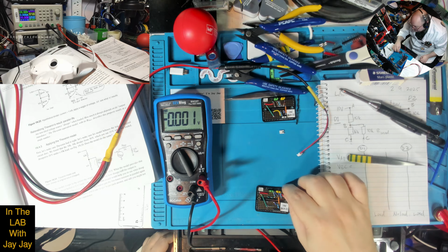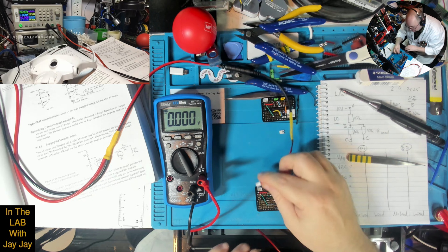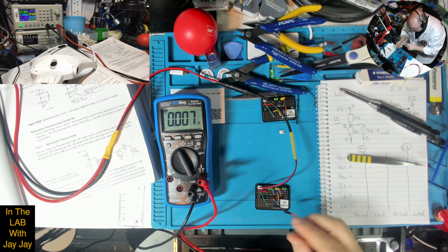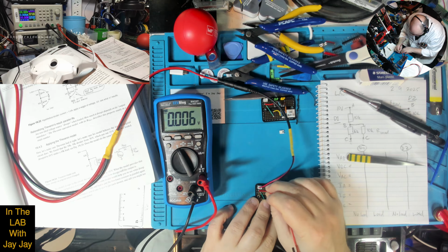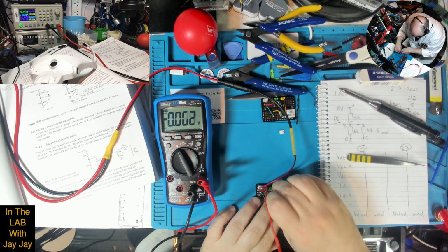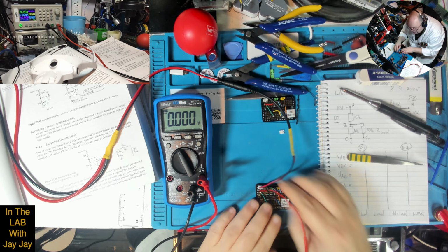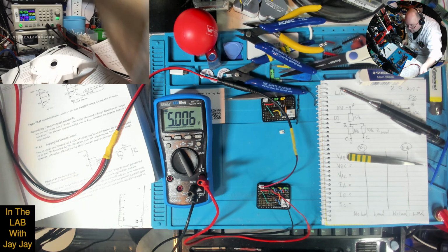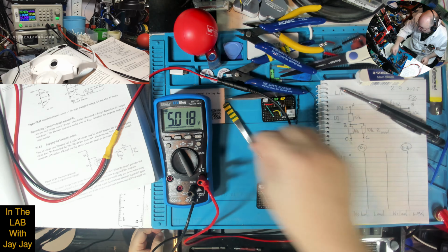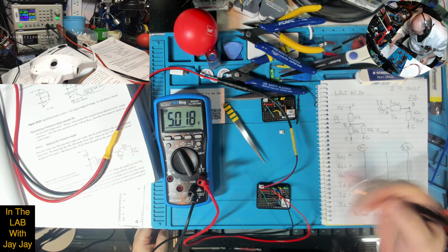All right. So I just put in that extra little jumper there. So let's attach power again, and we'll put on our probes. This time, hopefully, it will work. Put the positive one on there and the negative one on there, and that's testing the voltage across A and B. We're in voltage mode with power on, and we've got 5.018 volts, which is an encouraging reading, isn't it?